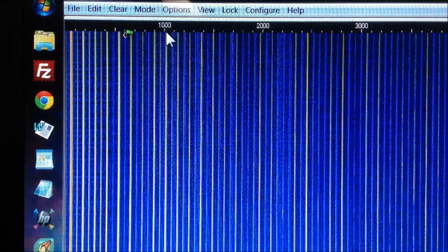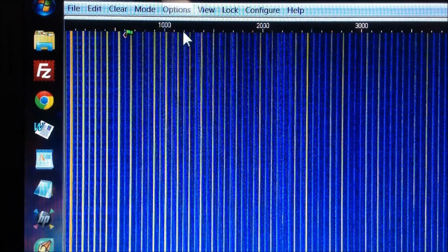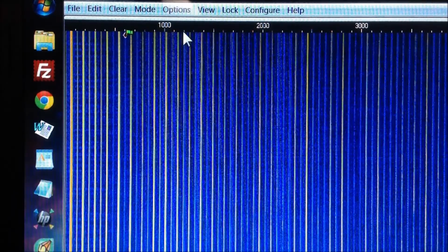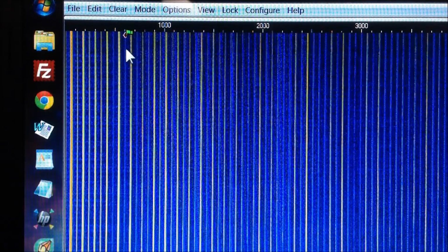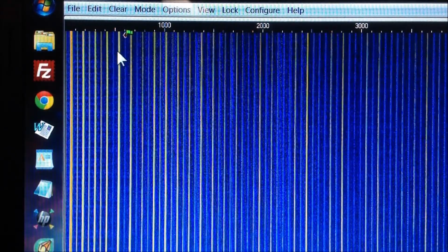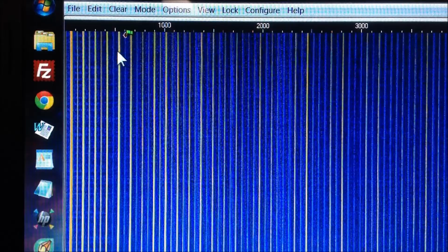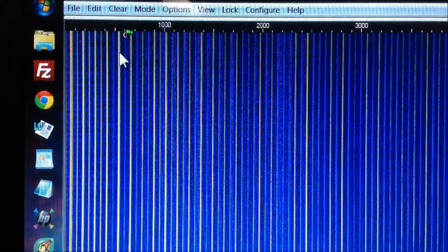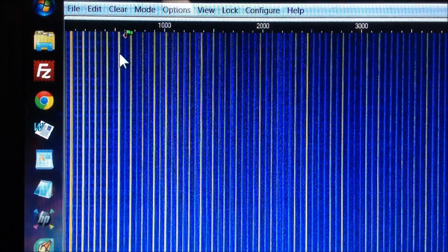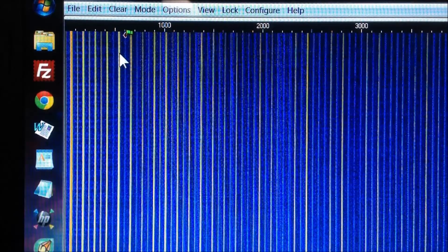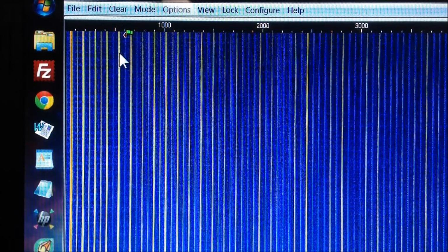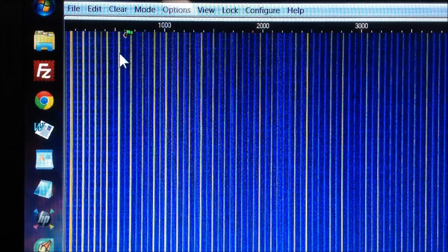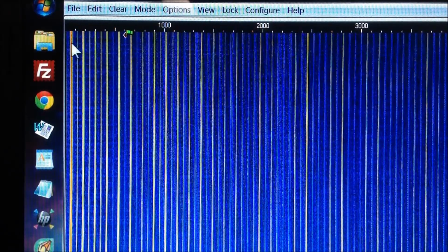We should see a line at 1200 hertz, which would be the 10th harmonic, and indeed we do, but it's quite dim. This bright one here is at, it looks to me like 540 hertz. And that line would be, I believe, the 9th harmonic of 60 hertz. That's a bright one. It seems the odd harmonics are the brightest.